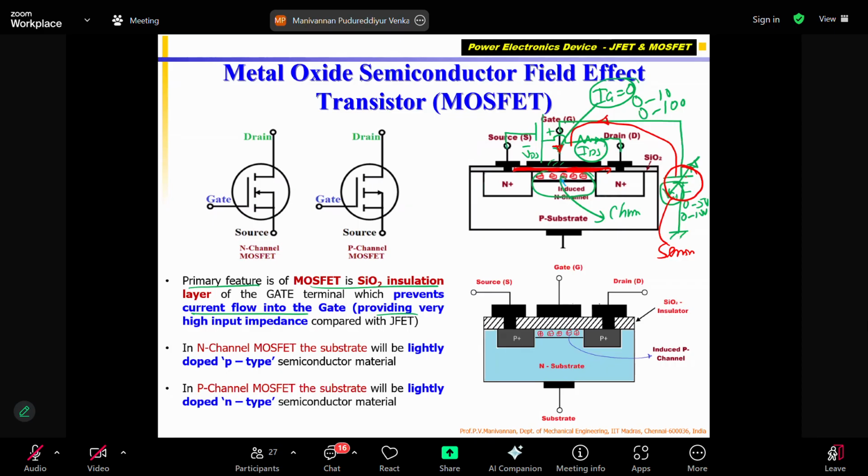When the sensor voltage provides to my electronic device, whether MOSFET or FET or transistor, where we are giving at the base of the transistor or gate of the FET or gate of the MOSFET, it should not consume current.